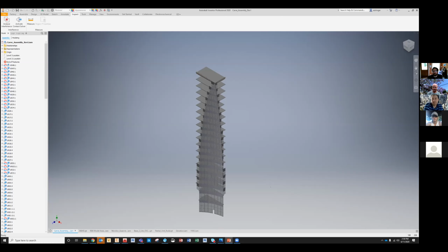You can use a lot of basic iLogic to drive the configurator that I was showing too. With the unit types, if you say this unit type, these parts are going to be on, or these planes are going to be this way, you can write pretty easy code that'll do that. You just click the drop down button and select the type, and it says, oh, you want these planes here and this stuff here, and it adjusts that. That's basic iLogic that isn't that hard to write.